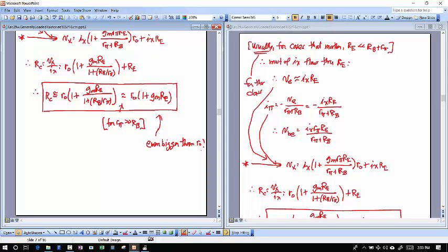And sometimes you need that very big when you want to make a current source or an active load or something that we haven't talked about yet, but you want a very large resistance. This is one way to get an extremely large resistance. In a lot of our analyses, though, this very big is just going to be swamped out by something much smaller, like an RC resistance that we have looking into this thing. And so we're rarely going to use this. Okay, a lot of times you're going to be able to neglect this. And so what I mean is something like this.